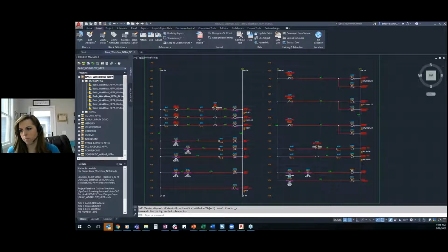Is it happening on every single file? Is it just maybe this specific project? From what I've seen, I have seen the unknown status before, but it was because of a specific issue with the workspace. It just wasn't aligned with what Vault was seeing. So I do know that the status icons work inside the project manager, so there must be something unique going on there. So I would just try logging out, logging back in, and see if that clears that up.